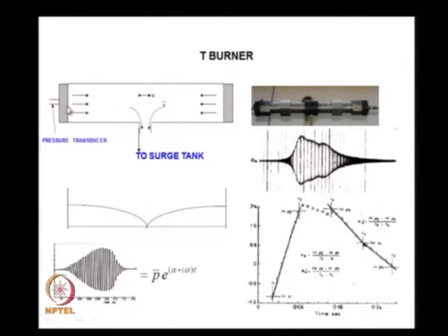you can maintain the pressure in the tube at any value we want. We also try to keep the length of the tube corresponding to the frequency of interest. We have already seen this earlier, namely the length of the tube will control the frequency of the oscillations which take place. Therefore, when the propellant is ignited at the ends and you have some disturbances, the waves tend to grow as shown over here till the propellant burns, and when the propellant gets burnt out, the damping effects in the chamber cause the wave amplitudes to decrease and it comes down.